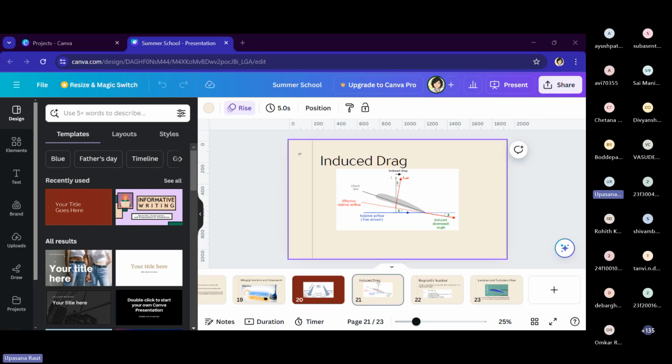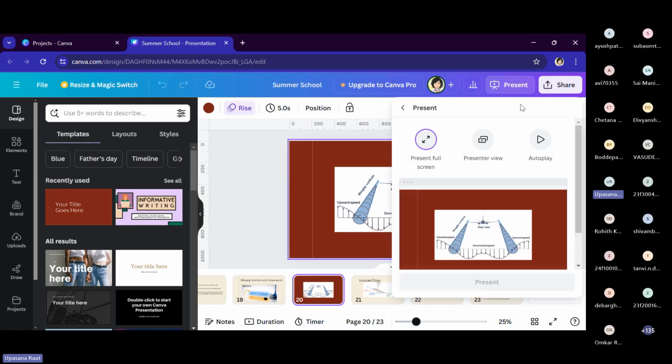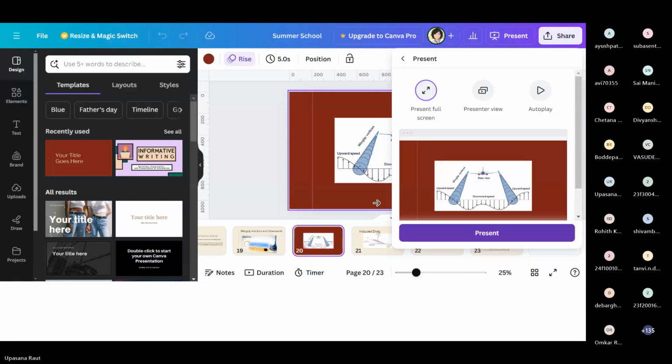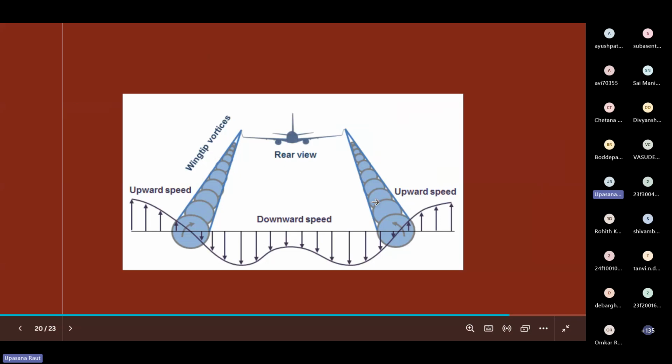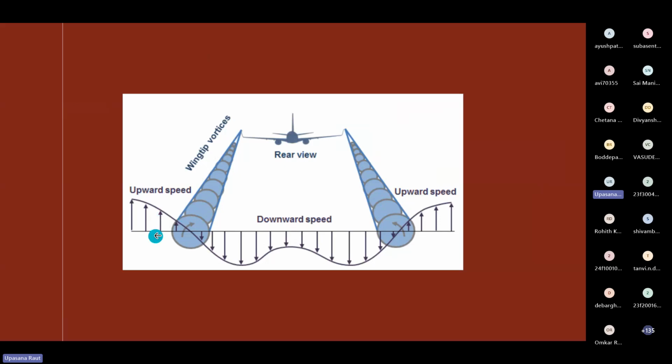It shifted because here the air was pushed downwards by the wingtip vortices. Let's assume there was no vortex and the air was supposed to go along a line, but now there is a vortex moving around inwards into the airplane. The vortex is basically air particles moving inside, so these air particles will be pushed downwards from where they originally were.